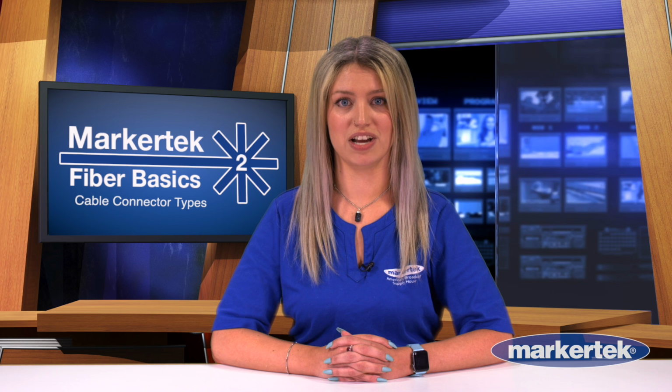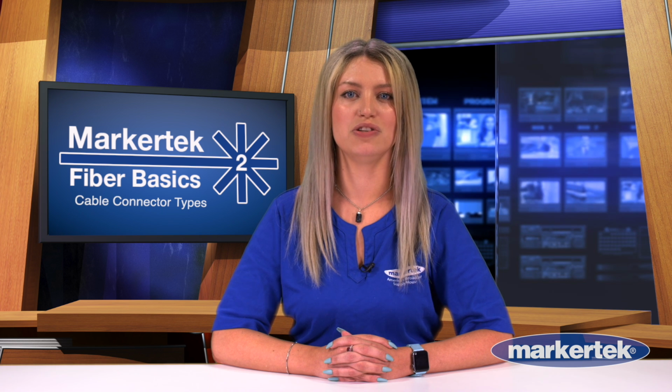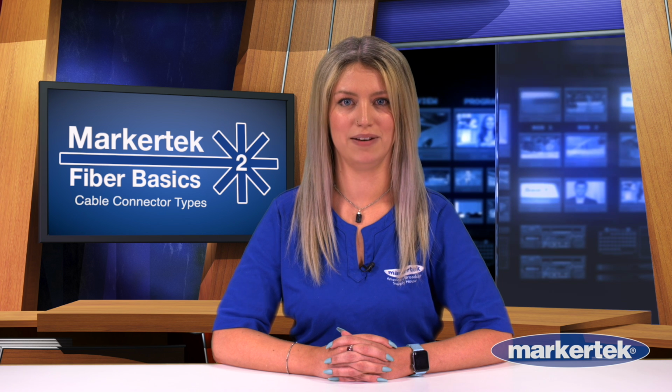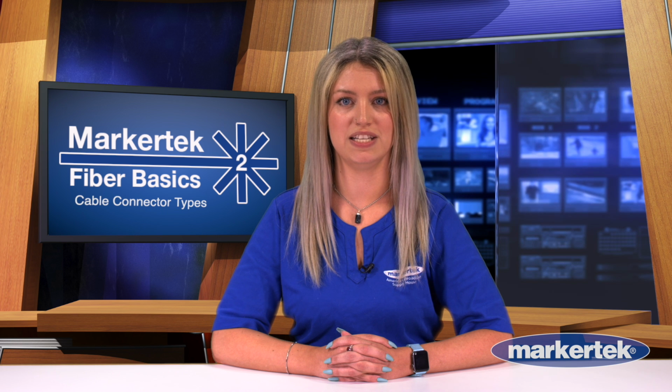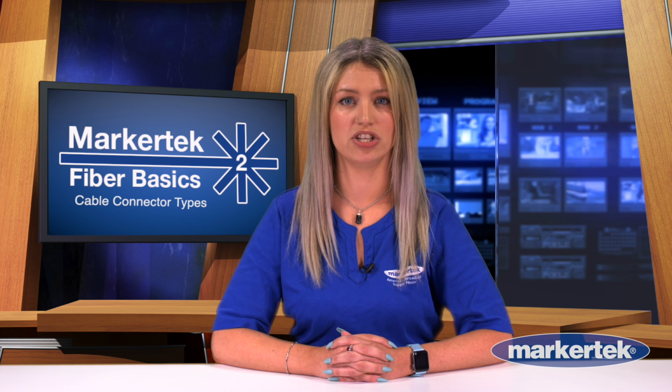All of these connectors are physical contact type connectors. That is, when connected, two fibers physically mate to complete the fiberglass connection and pass the light. Most standard traditional fiber cables will come with a UPC designation. In UPC, the fiber end face is polished and flat.